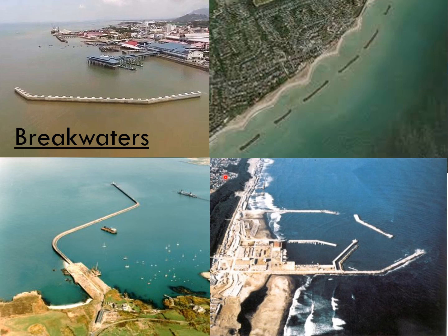More specifically, we notice that here we have a series of breakwaters which is constructed and oriented in such a way so that it creates a relatively sheltered inner harbor area in this part that is protected from the wave energy that possibly comes from all these different directions during different seasons of the year.